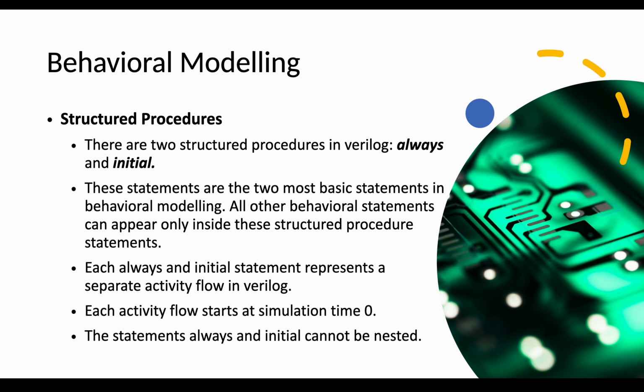First we will discuss structured procedures. There are two structured procedures in Verilog, always and initial. These statements are the two most basic statements in behavioral modeling. All other behavioral statements can appear only inside these structured procedure statements.